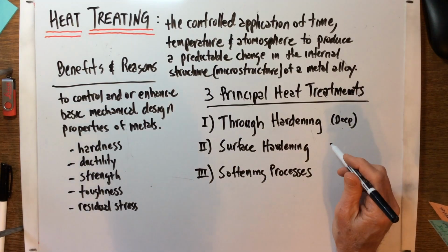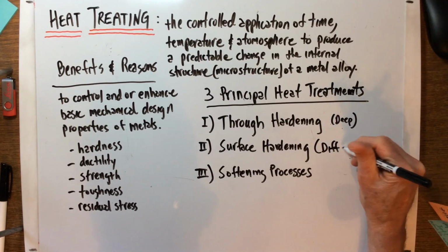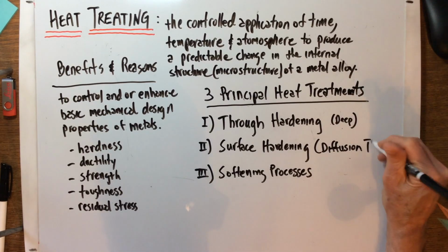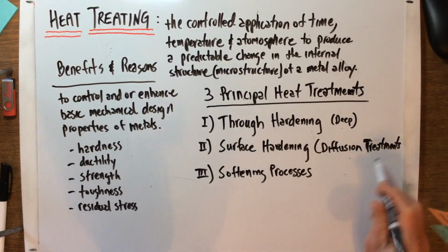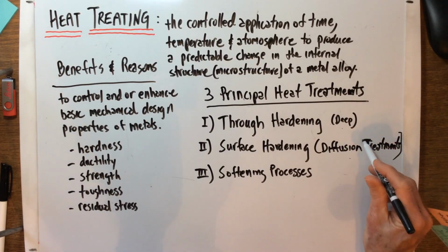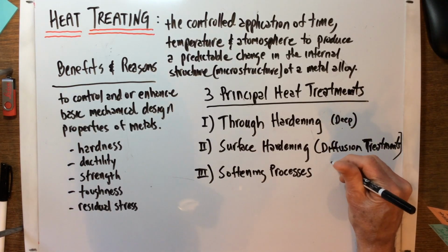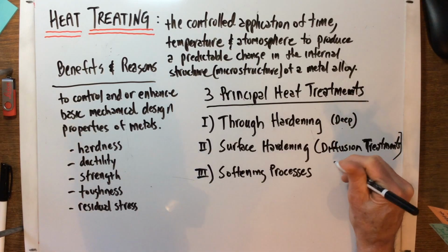All right. Now on surface hardening, we've got a couple of these surface hardening processes, what we call diffusion. These are basically taking advantage of Fick's first and second laws on diffusion. So these are diffusion treatments. I ran out of space there as usual. Essentially what we're doing is diffusing carbon or nitrogen into the surfaces of these parts, and they're generally referred to as carburizing.